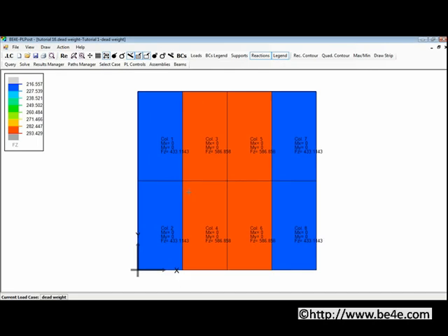Another use for the soil support is to model masonry walls by drawing a normal wall with its correct dimensions, defining it as a soil support, and then under select mode, right click to open the properties dialog box and change the Na to 10 and the Nb to 1, and then open the model into PL view to view the divisions, and this would represent a wall. And this concludes our tutorial.